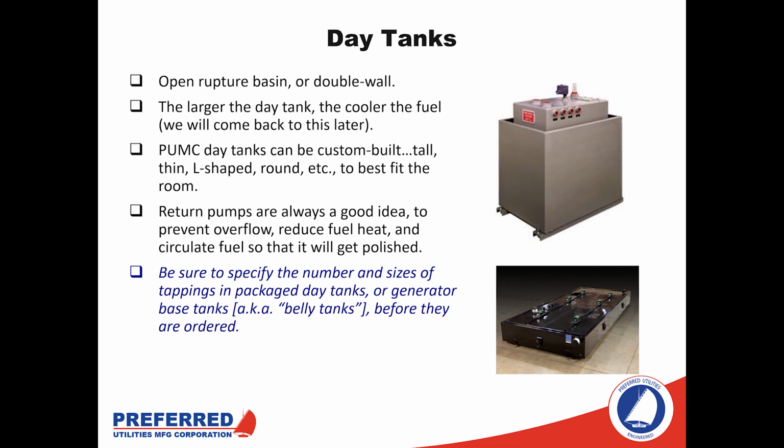Now, when we're looking at day tanks, obviously they can be any size or shape, whatever is best to be custom built for the application. And the components on there, we're going to have level control, leak detection, and in many cases, especially for mission critical applications, return pumps are a great idea. Now, from some design standpoints, people would see that a return pump is a potential for fuel being removed from a critical part of the system. But with proper design, proper safeties in place to prevent that, they actually add a lot of functionality to the system and far outweigh any of the downsides.